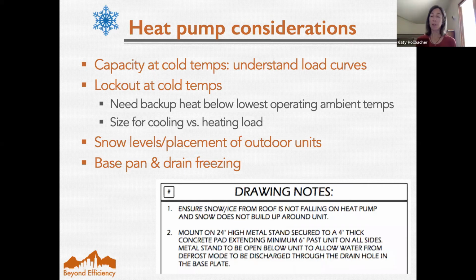I think you said that perfectly. And we have a chart on some of the Sandon coefficient of performance factor, COP, that will highlight how that drops. But I think you'll be surprised though, that while the efficiency drops, even at these really low temperatures, this technology has just evolved leaps and bounds the last 5 or 10 years even. It's still twice as good as electric resistance. And even if you completely get locked out, you're only in electric resistance mode, you're talking that happens a couple weeks a year. So on the balance it's still a really good way to go.